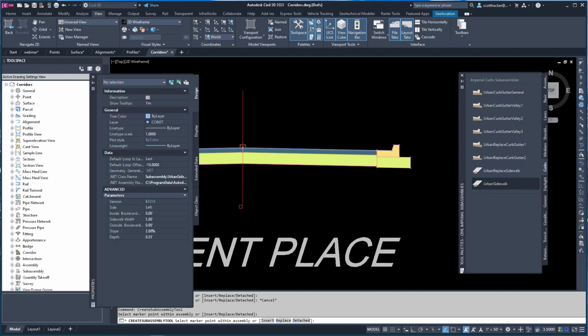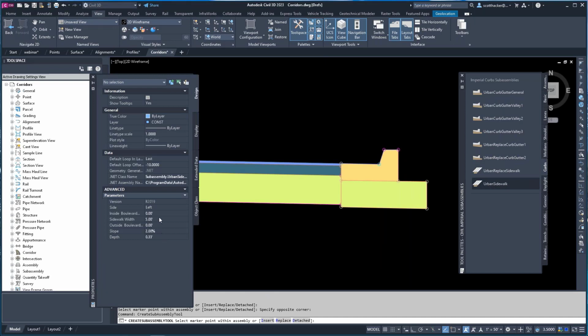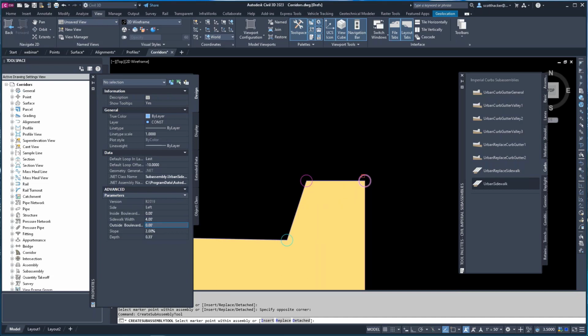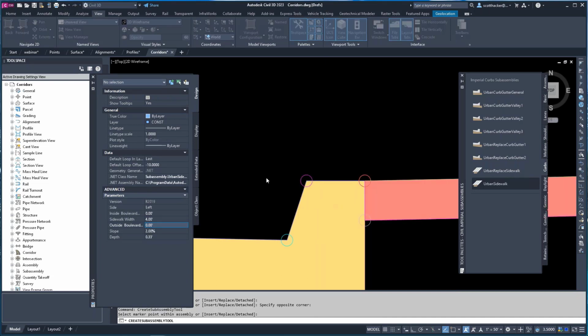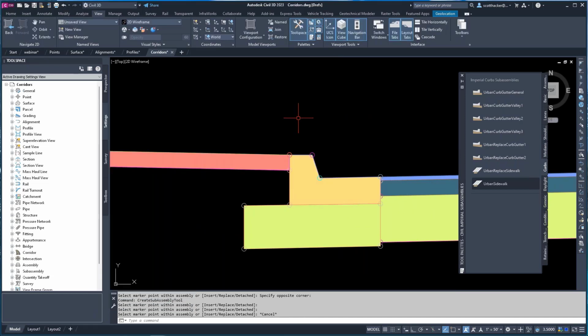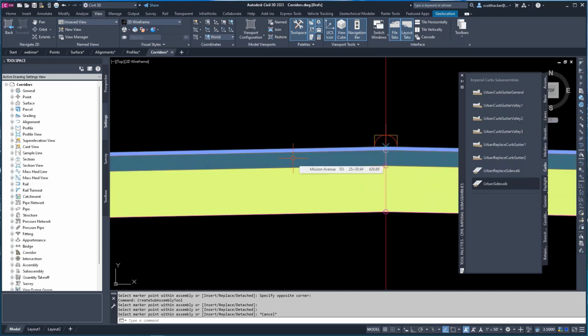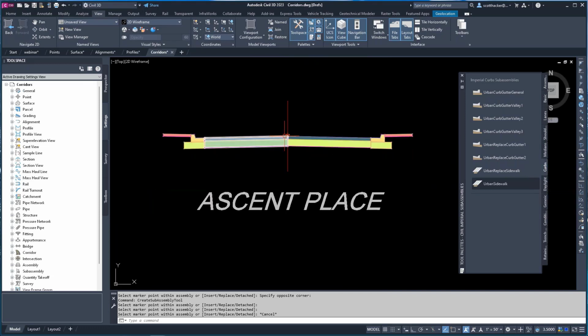Let's finish this up. We'll put in an urban sidewalk. The inside boulevard is 0. Since it's residential, we'll say 4 foot. And nothing outside on the back. Whoops. Fat finger there, 0, 4. Perfect. Drop it in. There we go. Okay. Pretty straightforward so far. Here's our lanes. They're 12 feet. We've gotten rid of the pavement course.